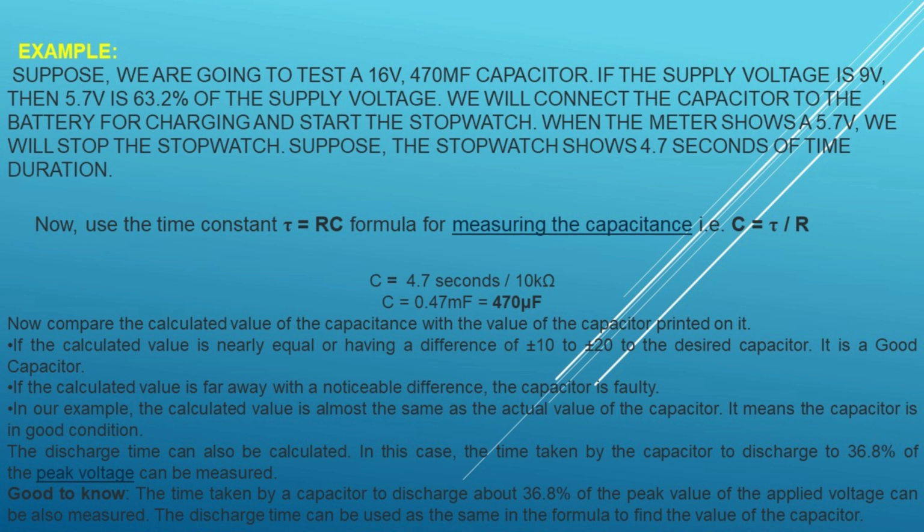Note that the voltmeter will show the reading for a very short time, as the capacitor will discharge its stored volts into the voltmeter. Note, the voltage rating of the capacitor should be more than the battery voltage. Otherwise, it will blast or burn the capacitor.